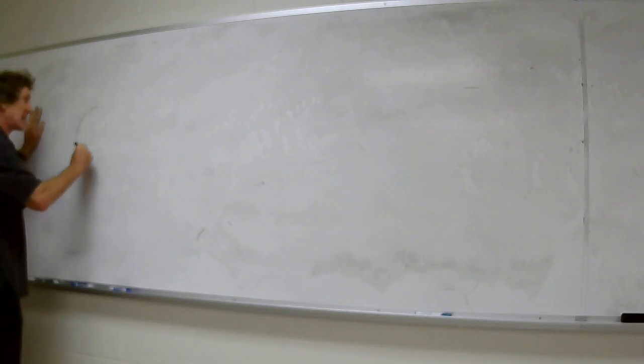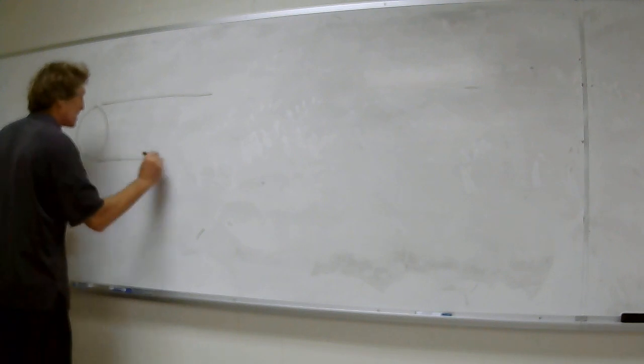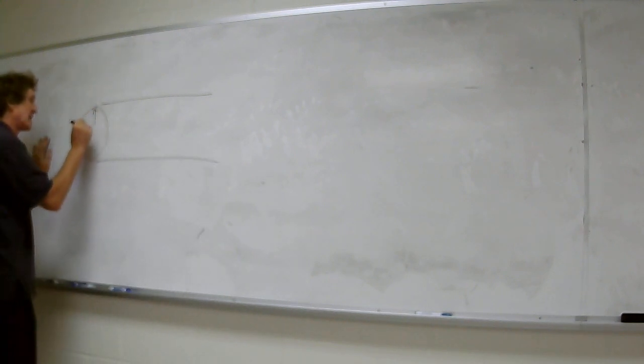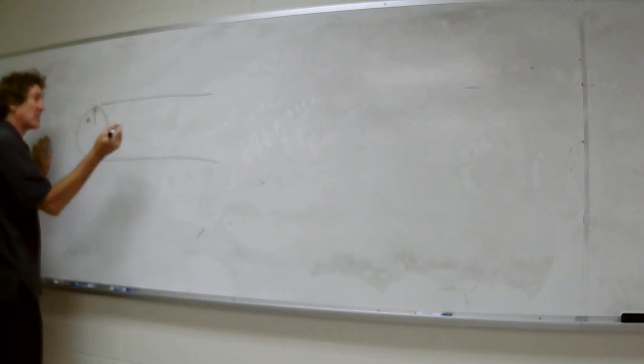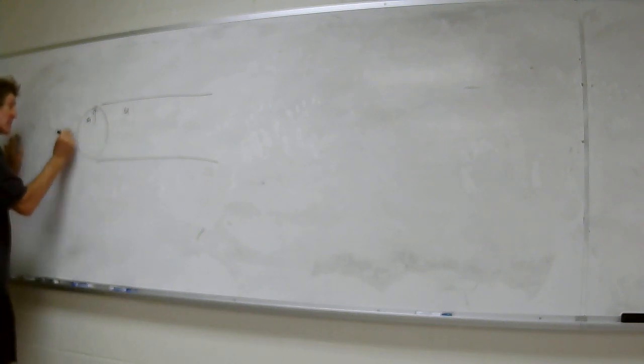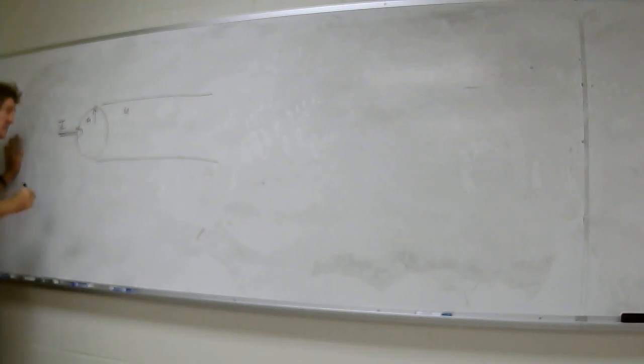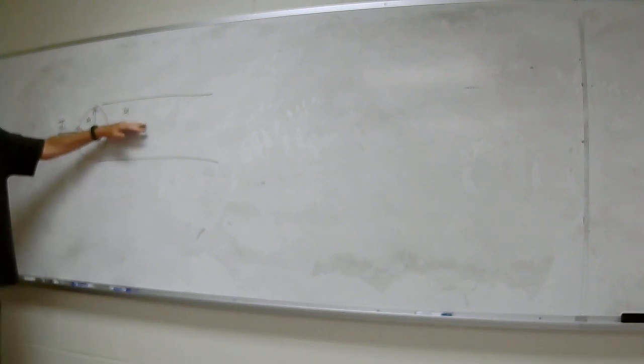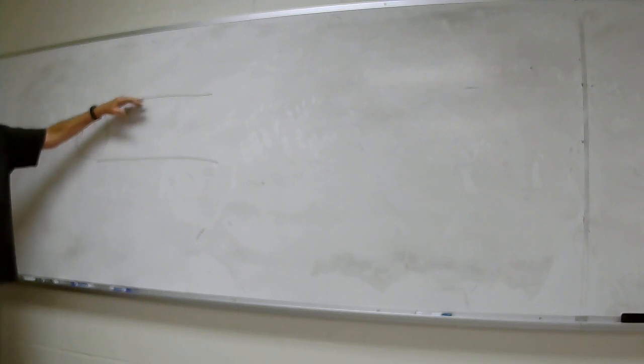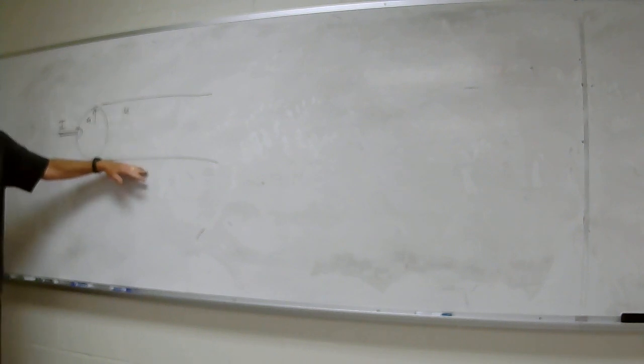Here's what it is. We're going to have a wire of a given radius A. It's going to have a permeability mu, and we're going to assume a current I is uniformly distributed in here. All right? So now what we're going to do is calculate the H field inside the wire. And we're going to find out the magnetic energy density inside the wire. We're going to get the self-inductance per meter. Do you all follow me on this, class?